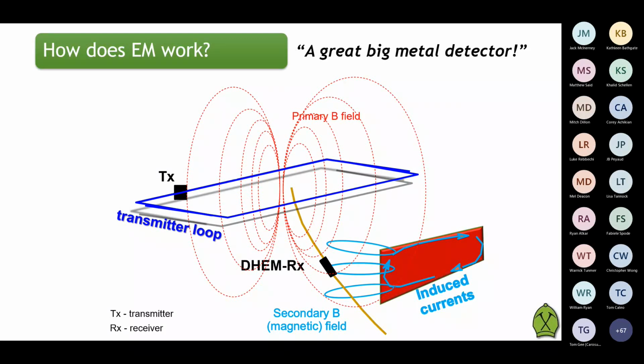And every magnetic field, when it's changing, generates currents. So they're one on the other. That's how we can use magnetometers to measure electrical currents in the ground. It's the interaction between electricity and magnetic fields that is basically the fundamental of EM. So this electric loop, which is just a loop of wire, usually insulated wire because it'd be messy if it wasn't, has electrical current flowing around it, and then that current is turned off as fast as we can make it turn off.